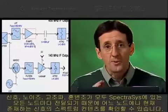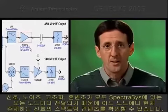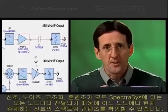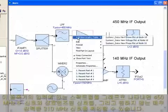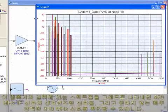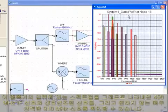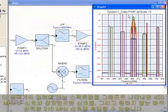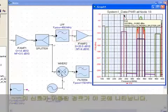Since all signals, noise, harmonics, and intermods are propagated to every node in Spectrasys, you can see the spectral content of the signal present at any node. When I plot the spectrum present at the input to this amplifier and zoom in on the graph, you can see the 450 MHz IF signal, intermodulation products, and a very strong unwanted 310 MHz signal. The path this signal traveled is shown here.